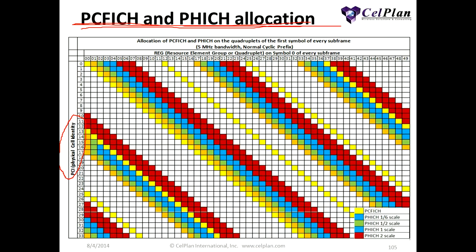Depending on the PCI, the idea here again is to avoid that neighboring cells have the same channel in the same place. You still will have interference between different channels. You have traffic channels, you have control information, but you try to avoid that the same code that you are using here, the same spreading code, is repeated in neighboring cells.